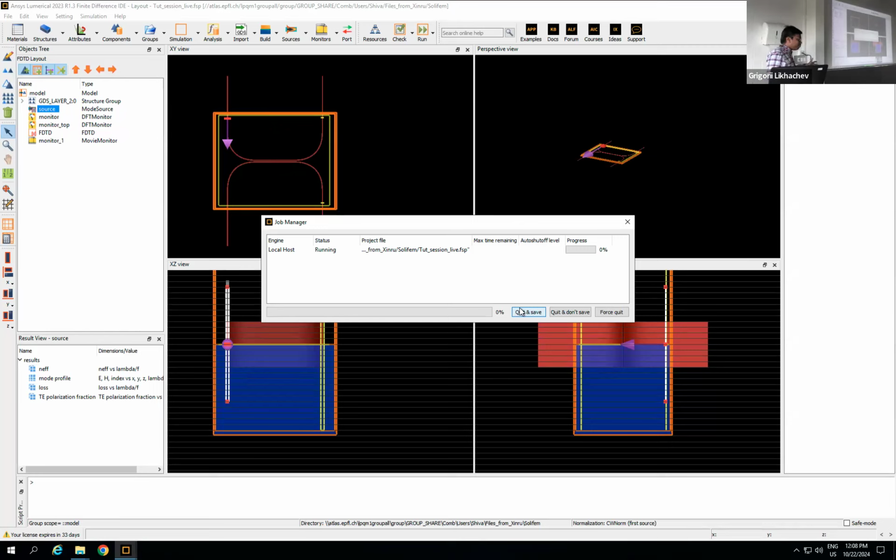Basically, I tried to optimize the device parameters, coupling length as 30 and waveguide width as 1.4 micron. This is not realistically correct. This device won't work, but it will help you guys to simulate it faster. Okay, so it will take some 10 or 11 minutes to run. But then, okay, I think I was a bit slower because it went more than 14 minutes, but if they start doing the simulations, it will take a bit of time.